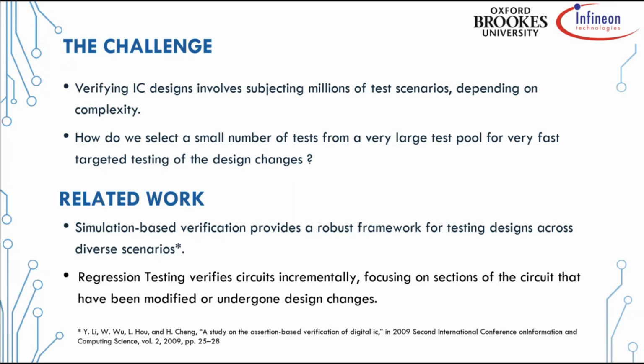And the related work around this area would be simulation-based verification, which basically offers a framework to test designs across multiple scenarios in a particular IC. Meanwhile, regression testing also focuses on specific sections of the circuit that have been modified, making it more efficient to verify the change you made without retesting the entire circuit every single time you need to do a test.